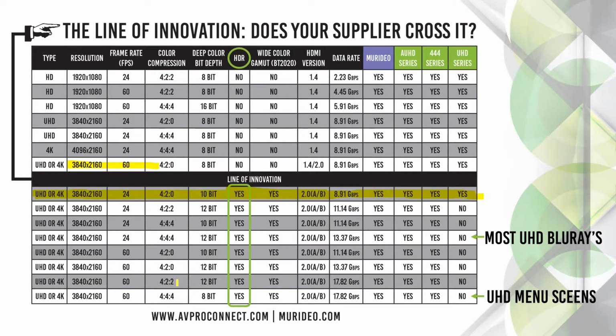A lot of guys say, well, okay, I'm under 10.2, so I should be able to use a UHD player, or I should be able to use my HDBaseT extenders, and I won't have any problem. The problem is this format. If you happen to be lucky enough to own an Oppo, where you can tell what the native resolution of the disc is and the output resolution of the player, you'll see that this is native UHD disc resolution, this first highlighted line here. No TVs can reproduce that signal.